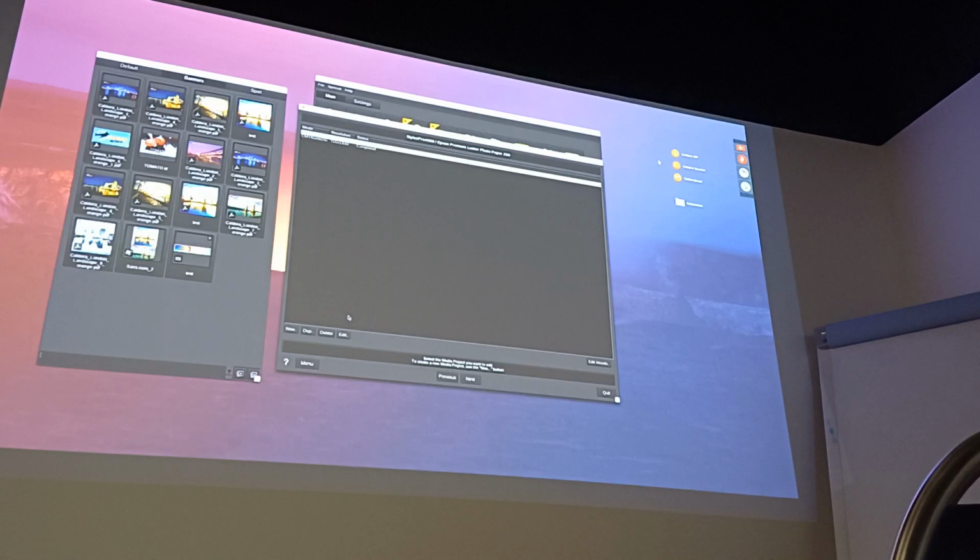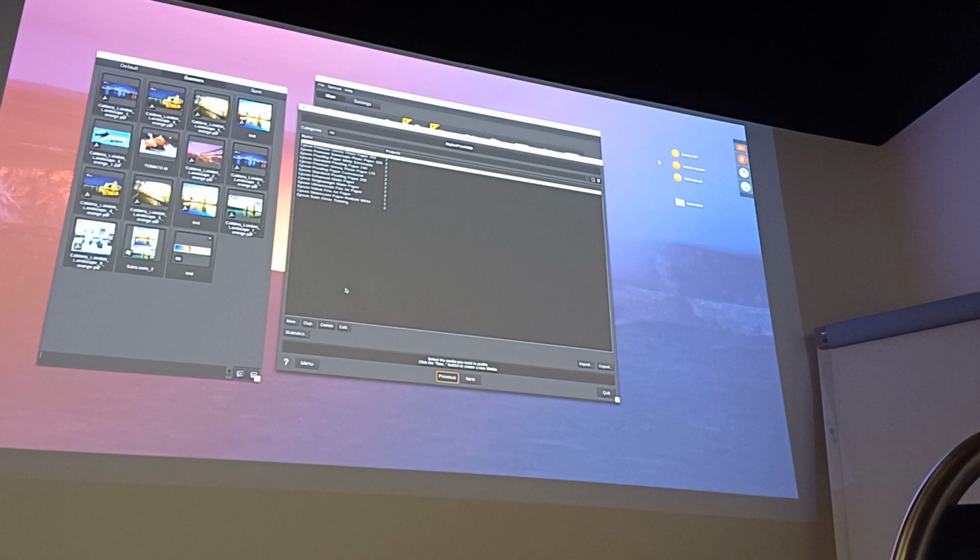So this is what I'm going to do. I'm going to go previous, and I will create a brand new media. So let's click new. Here is where you can name your current project or media. Of course, as you probably know, when we are creating an ICC profile, as I told you before, we really want to calibrate the printer with a specific substrate. So usually we give the calibration the name of the substrate. So here would be, for instance, PVC banner.